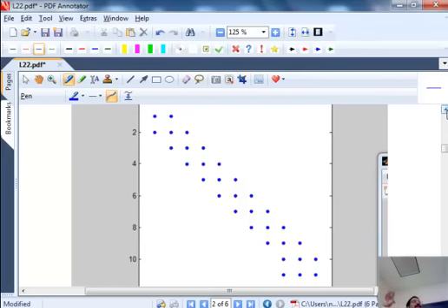But when you have an insulated tip, theta 0 is still known, it is always 1. But on the right hand side, we don't know what the temperature is, because the profile that we are going to calculate may look like this or may look like that. So the temperature at the tip is going to depend on the value of m that we put in. It's an unknown. So the unknown set increases to 11. Instead of 10, we have 11 unknowns. And we have to have the 11th equation.